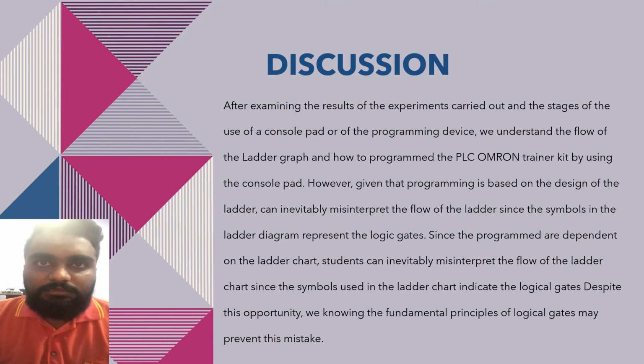Next is the discussion. After examining the result, given that the programming is based on the design of the ladder, students can inevitably misinterpret the flow of the ladder chart, since the symbols used in the ladder diagram represent logic gates. Despite this, knowing the fundamental principles of logic gates may prevent this mistake.